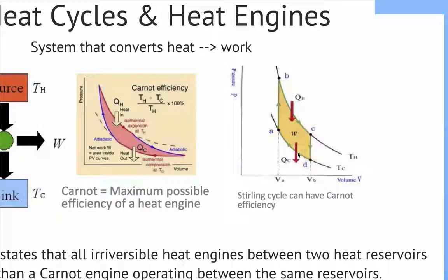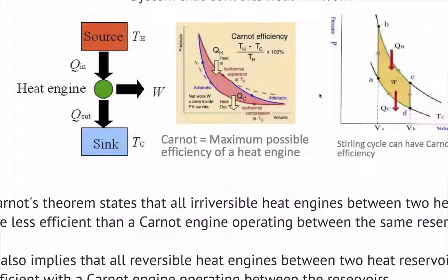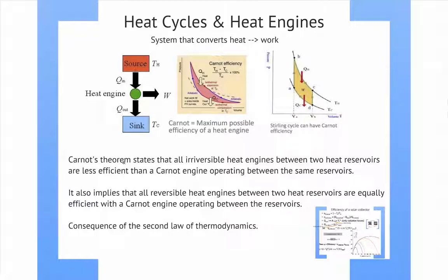constant volume, and then there's a compression. So this compression happens isothermally as well at a fixed temperature Tc. So during these vertical lines, of course, no heat transfers. So that's why this is adiabatic, similar to the blue portions of the curve, and there's no heat going in and out. But during these expansion and compression, heat comes in or heat goes out. And the difference, of course, is the work done, which is the area under this curve. So it's just a different cycle, referred to as the Stirling cycle, and the difference is that there's this constant volume phase of it.